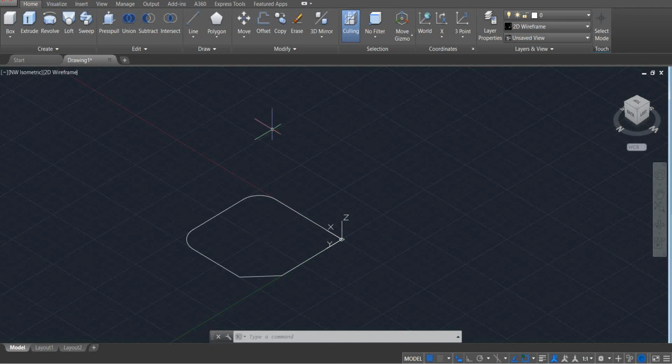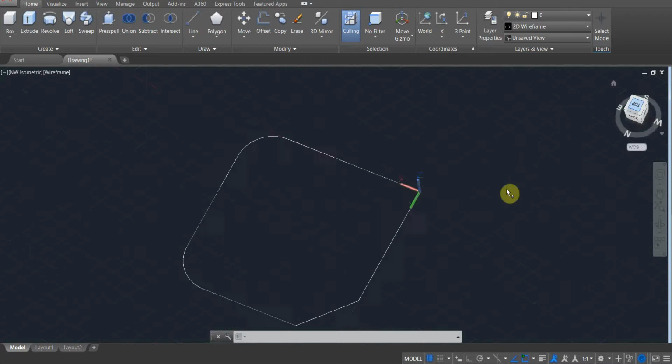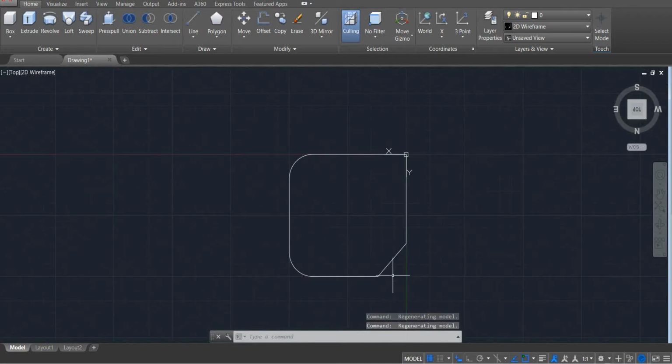But there are some things that we have to do, and there are some points that we have to demonstrate here. This two-dimensional sketch is conditional. So what does it mean? To end up with a solid, this two-dimensional sketch, first, should be closed. It should be a closed loop. So what does closed loop mean? If you start from any point and move all the way, you're going to return back to the same point. You can start from here and move in this direction, or even the other direction, and you're going to return to the same point. So it means that the sketch, generally, should be a closed loop, as already given here.